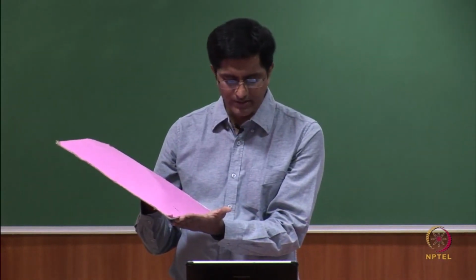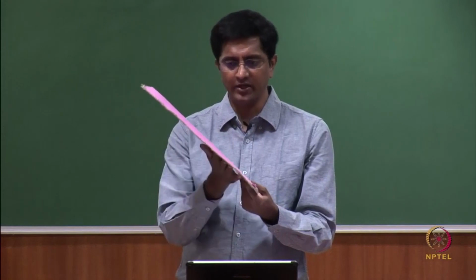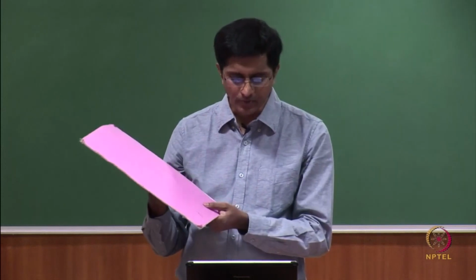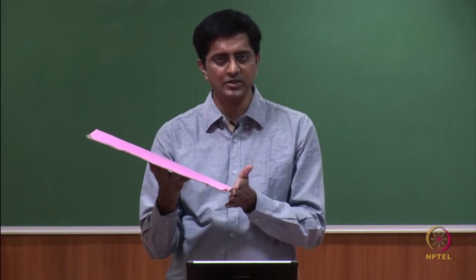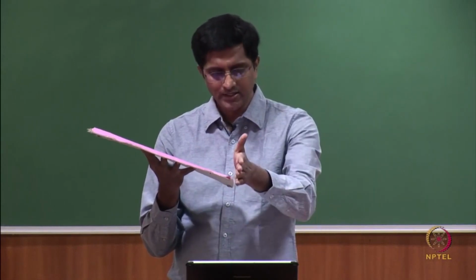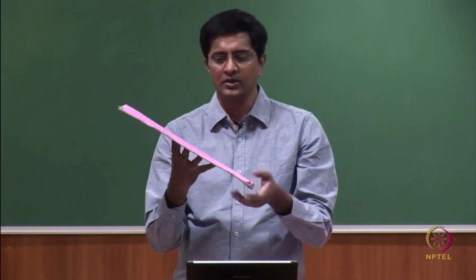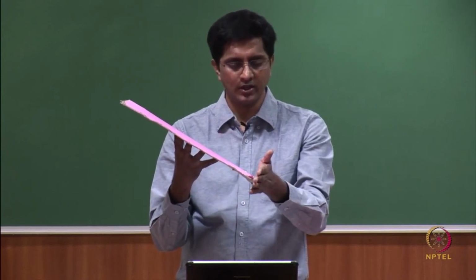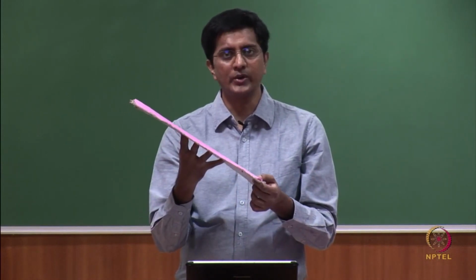What else do we know? The surface of the plane is inclined at 60 degrees to the horizontal plane. So, which means this plane makes an angle of 60 degrees. So, this angle is 60 degrees. It also says that it is perpendicular to the vertical plane. So, let us say now this is the vertical plane. This short edge is perpendicular to the vertical plane. So, this meets the description of the question, saying that we want a rectangular plane which is at an angle of 60 degrees with the horizontal plane and the short edge perpendicular to the vertical plane. So, how do we draw the projections?